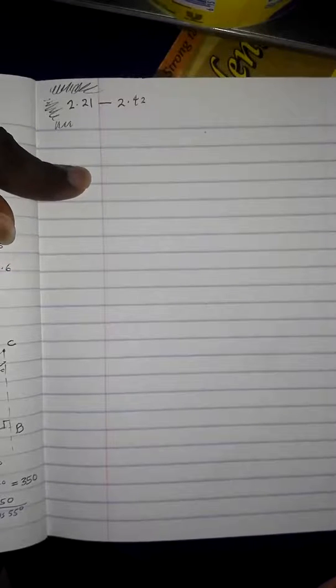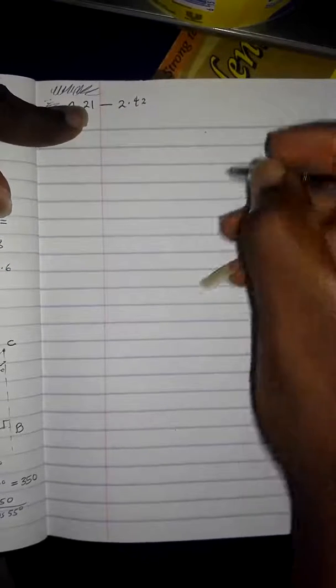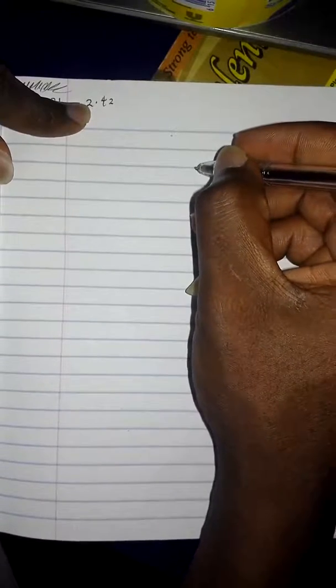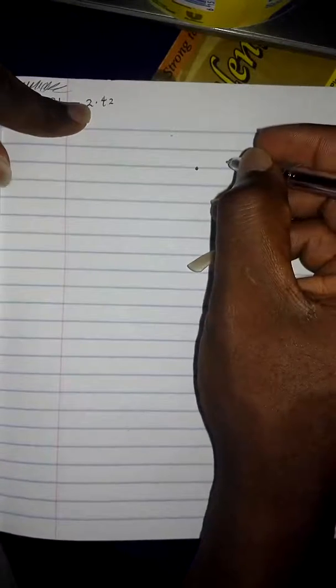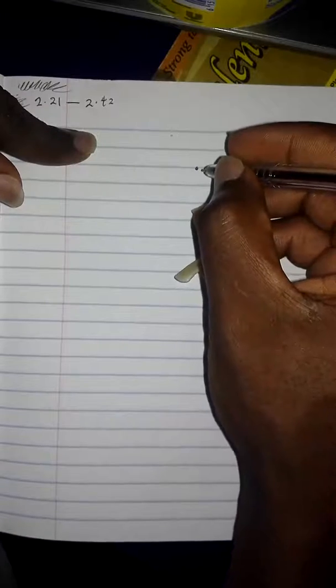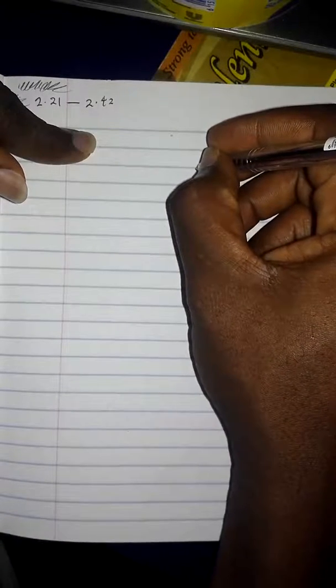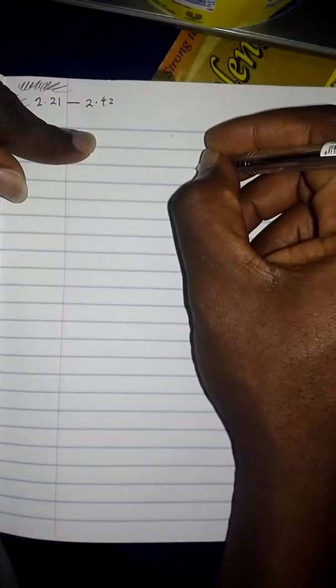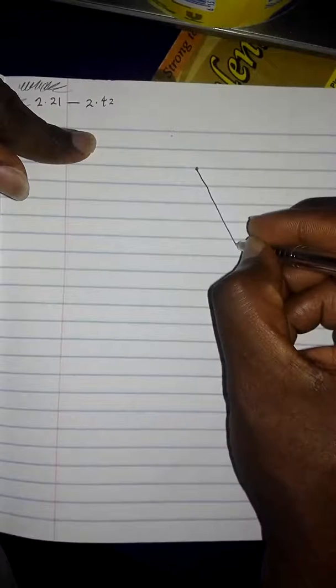Okay, so we'll pick the point of interest. We first produce an illustrative diagram. To do that, we pick our point of interest, that's point C in this case, and then we show the forces acting on point C. We are told that we have a 75 pound force. So we draw that, this 75 pound force.